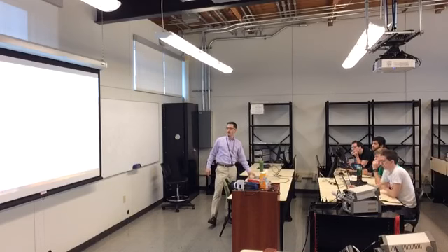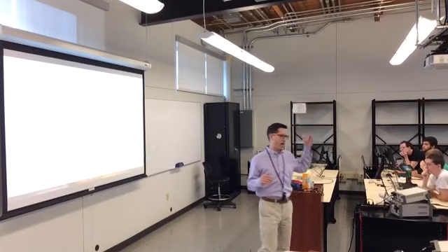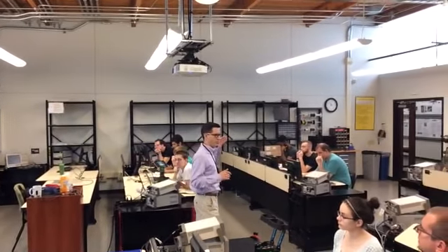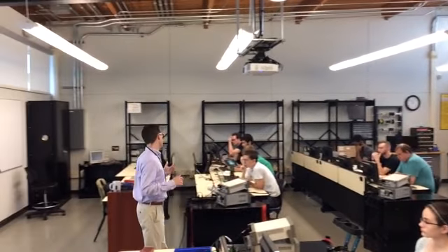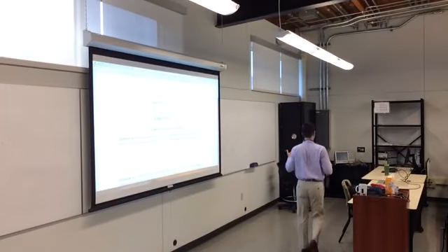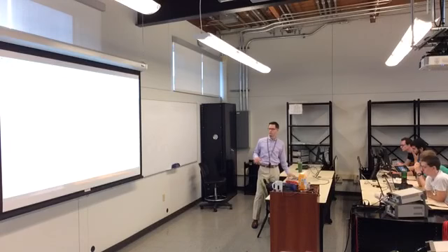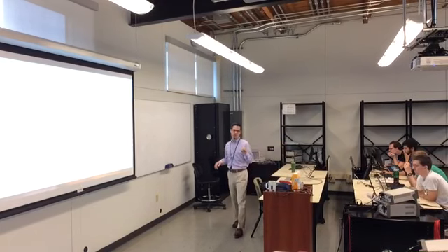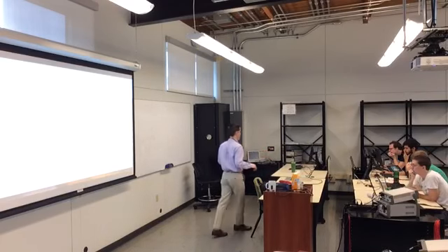Important things about the structs. Remember, the structs are laid out contiguously in memory. So if I'm pointing to the top of the struct, and let's say it's at 100, and I have a 32-bit object immediately in the struct, the end of that object will be 4 bytes away. Everything inside the struct is contiguously laid out in memory and will be in order. And that is how we get the data structures for the GPIO, the timer, everything else we use. They're always structs because they're always laid out linearly in memory.